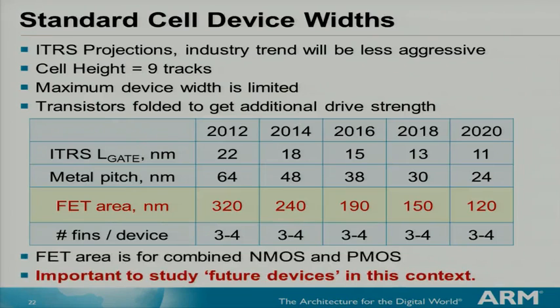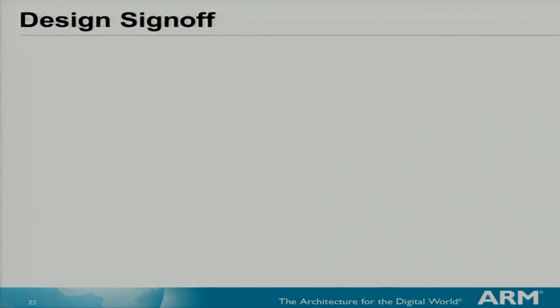And that's a very important observation, because most of the device-related research papers that come out will show you a device which is 1 micron wide. It is the minimum length transistor, but it's 1 micron wide. But what designers really need to see are very small width devices, because that's what they're going to put in. This is true for digital design; I'm not talking about analog design here. But for standard cells and digital design, it's very important to see very small width devices and the different second order effects that come around with these small devices.